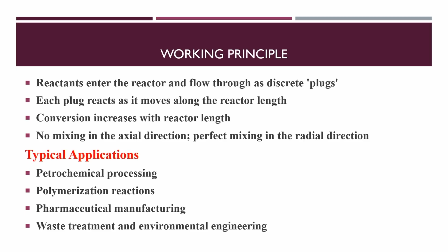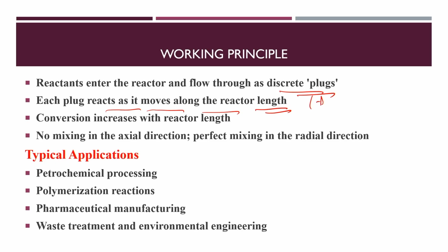The reactants enter the reactor and flow through as discrete plugs, and each plug reacts as it moves along the reactor length. So, here the dependent variable is considered as length in place of time, and conversion increases with the reactor length, and as this is a plug flow, there is no mixing in the axial direction.